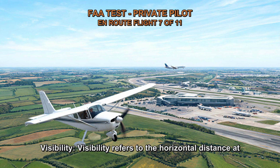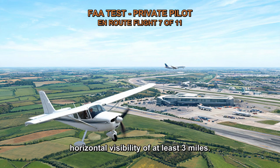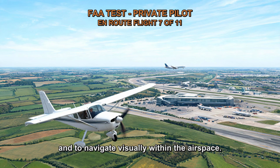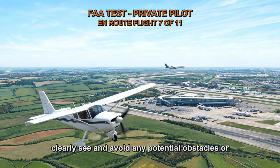Visibility. Visibility refers to the horizontal distance at which objects can be seen and identified. In Class D airspace, the visibility must be at least 3 statute miles. This means that pilots should have a clear horizontal visibility of at least 3 miles. Meeting these minimums ensures that pilots have adequate visibility to maintain safe separation from other aircraft and to navigate visually within the airspace. It also helps to ensure that pilots can clearly see and avoid any potential obstacles or hazards during their operations.